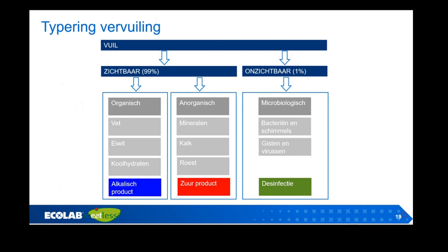It depends. No, that's not right. There should always be an intermediate rinse between the acid product and the disinfection. The danger is when you mix, the most dangerous being the alkaline product and the acid product. I will tell something more about it later, but you always have to rinse between the chemicals.